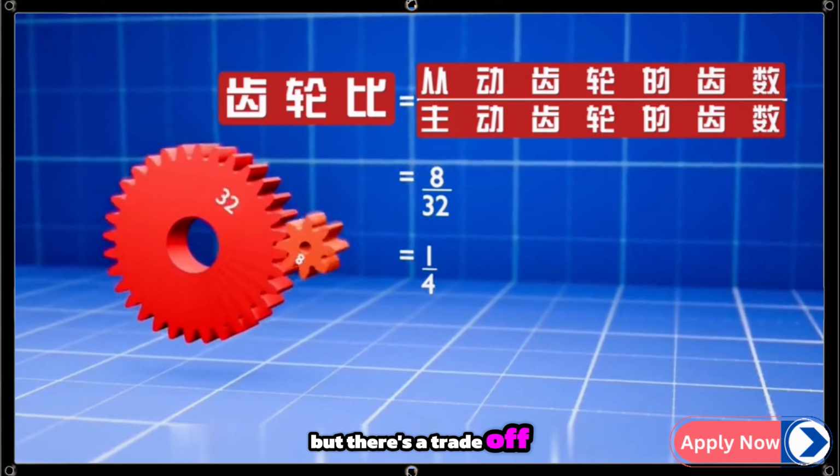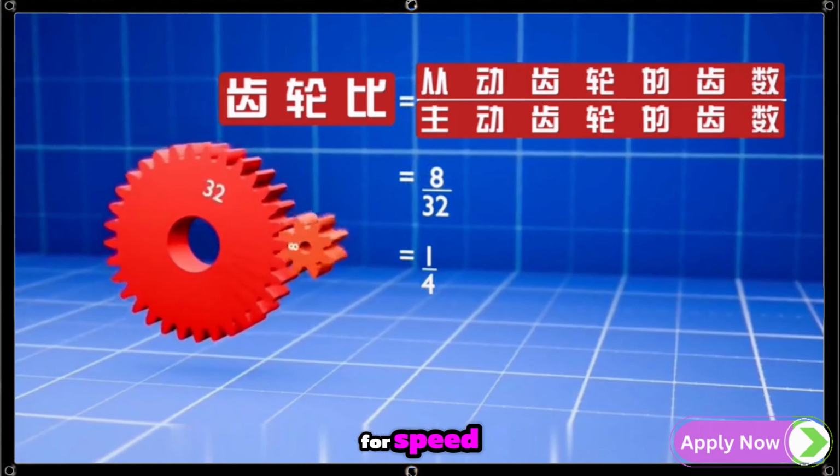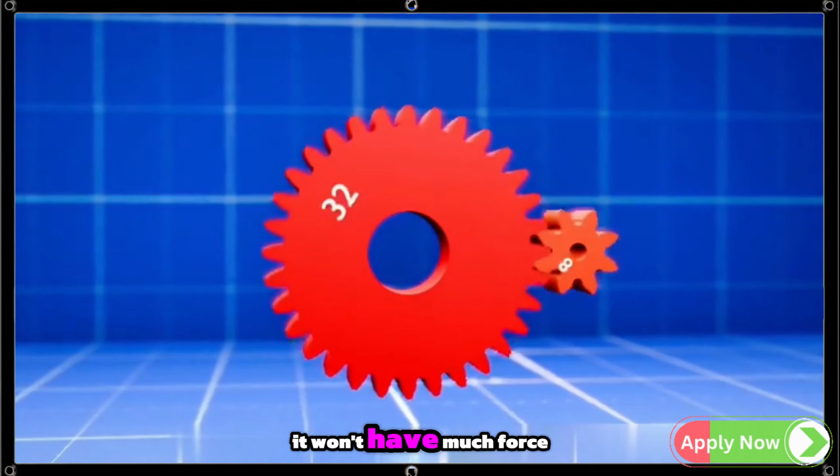But there's a trade-off. While speed increases, force decreases. You sacrifice power for speed. Even though the pinion rotates 4 times faster than the larger gear, it won't have much force.